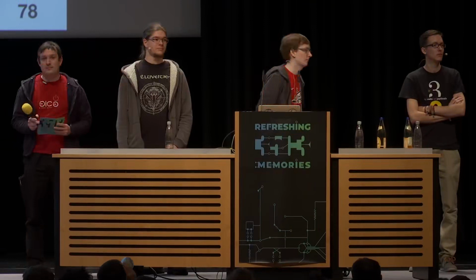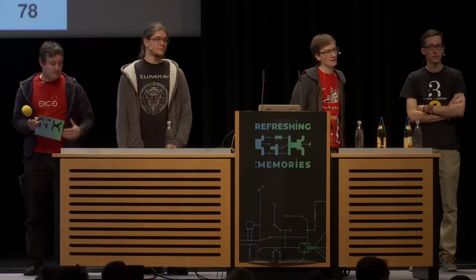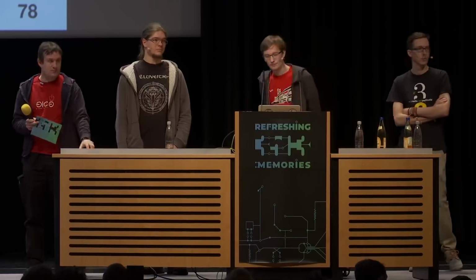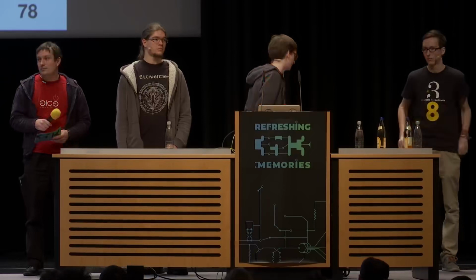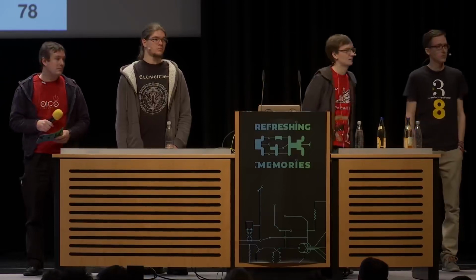Thank you. Microphone number 1, please. So how do you deal with I/O ordering? The x86 will guarantee you that the order in which the CPU posts I/O accesses is the same as the device receives them, but on other platforms this is not the case. Yes. And if you do it with UIO, the UIO doesn't give you any such guarantee.